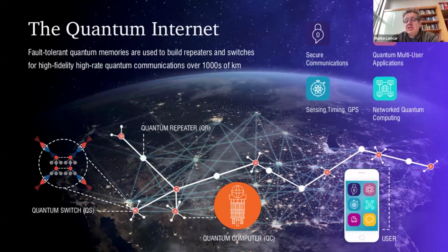In a classical communication system, you can tolerate some amount of loss because you can always amplify the signal using, for example, erbium doped fiber amplifiers. But in the case of quantum signals, when the information is carried with a single photon, this is impossible, for the reason that ultimately makes this quantum communication channel secure, which is the fact that quantum information cannot be copied, cannot be cloned. So great care needs to be taken for these photons not to be lost while they propagate